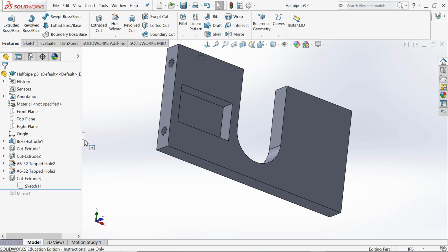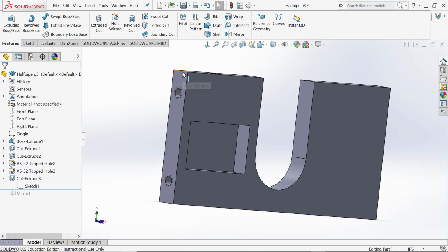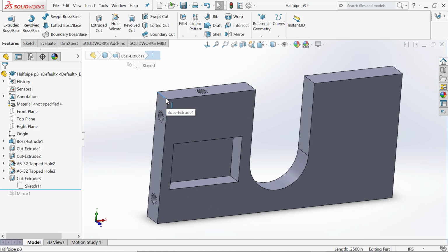So what we need to do now is, if you noticed when I first brought this up at the beginning of class, these were not sharp rectangular corners here. Instead, this was sort of rounded off. Now, that's called a fillet. The fillet tool is interesting because it does two different things depending on the kind of edge you click. If you click an edge like this, where it's solid bodies coming to an outside corner, much like this corner is here for Tommy, he can see. If you were to do a fillet on that edge, it would actually remove material.